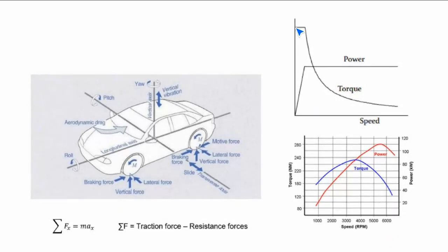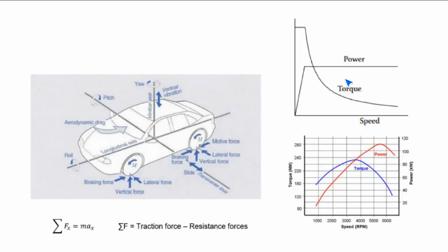Normally, in an electric vehicle, we have a flat side, and then torque will be reduced, speed will increase, and power will be constant. After that, torque is decreasing. Okay, you can see this on your screen. Please follow my arrow. This is the constant power region in the electric motor. Also here, constant power region. In an electric motor, we have two working points, constant torque and constant power region.